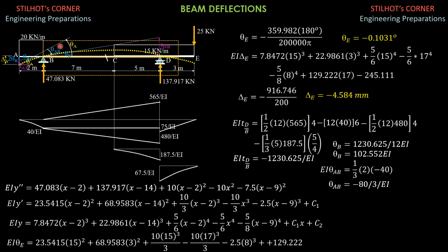So this is negative, so it is clockwise. So this is the tangent at A, then the tangent at B, this one. So that's why you have theta AB. That's the direction, that's clockwise because this is negative. But this is treated positive here. And this is theta B. The angle that the tangent at A makes with the horizontal is theta A. And that is positive from the figure. Therefore, theta A is absolute value of theta AB plus absolute value of theta B.